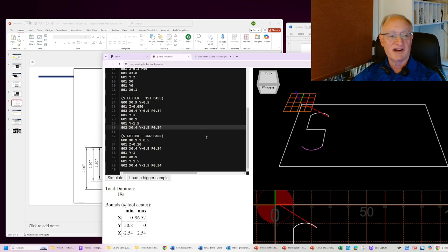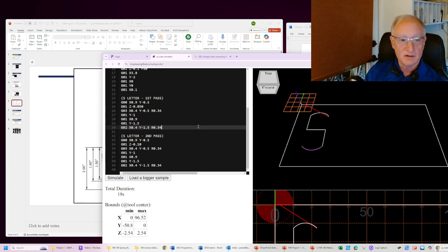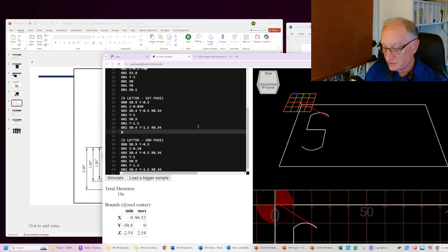So I got to raise up by G01. We could do a G00. I'm just going to do a G01 so I don't get the machine too excited. To height of 0.1, I know I can clear. And from there, once I lift up, I know I can get over to this area.